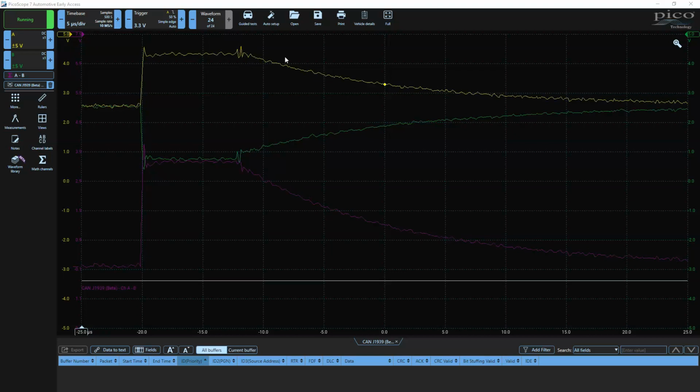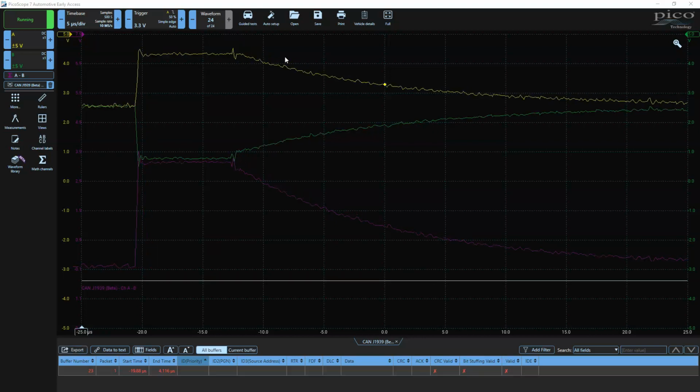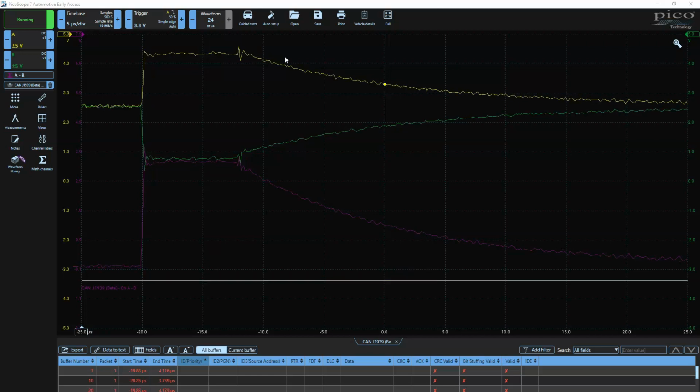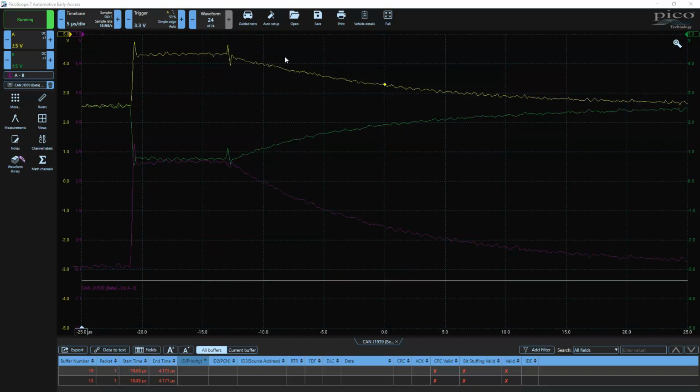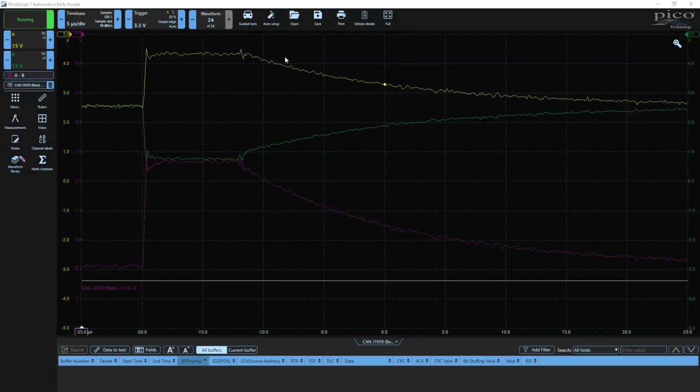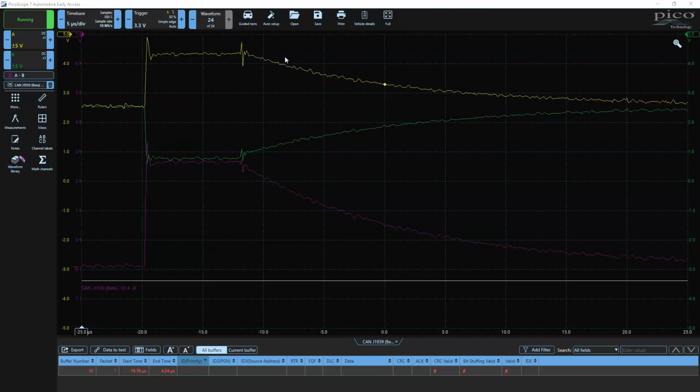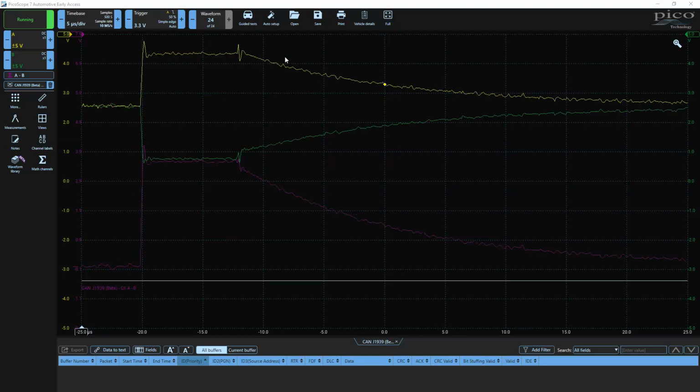And I myself, as a test engineer in the past, there's been plenty of times that I've put another 50 feet of CAN network on because I had something in a cold cell or a cold chamber, a truck or machine, and I needed CAN information outside of it. And so, yes, I violated the standard, but I'm what you call an expert, right? So I knew that it wasn't causing a problem, and I could scope it and I could see that it was well within the fault time that we needed.